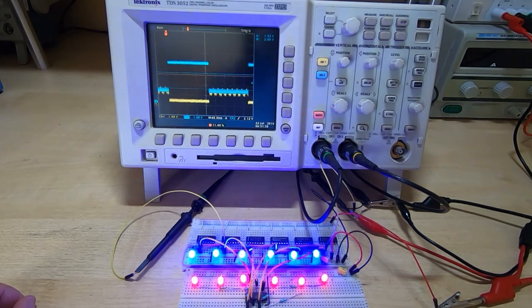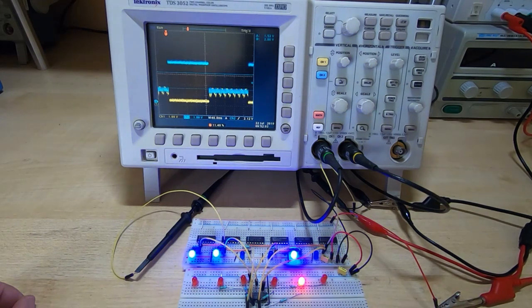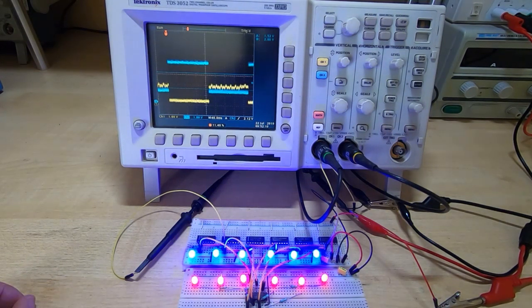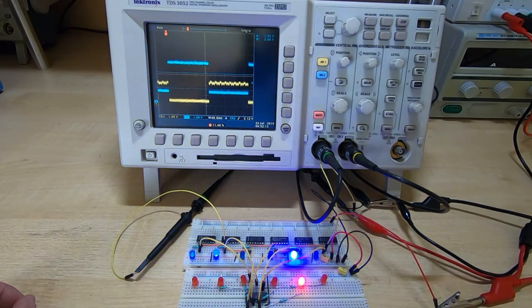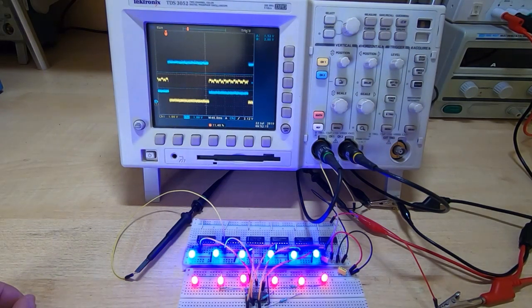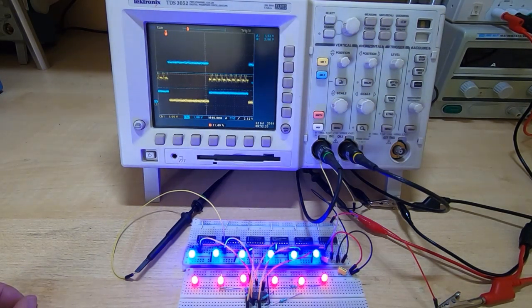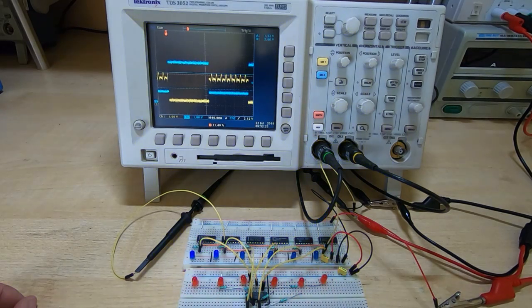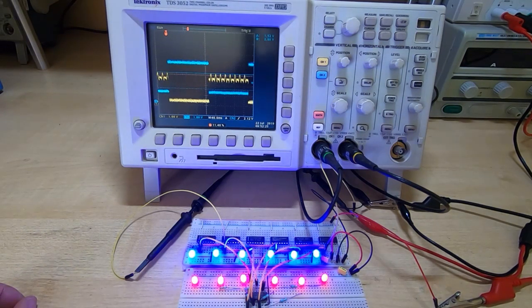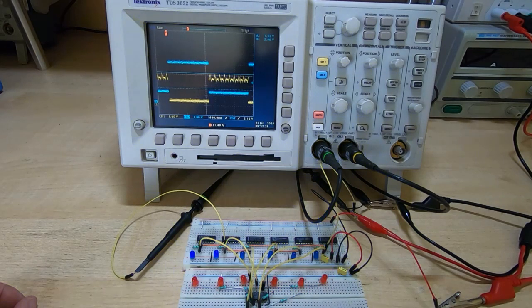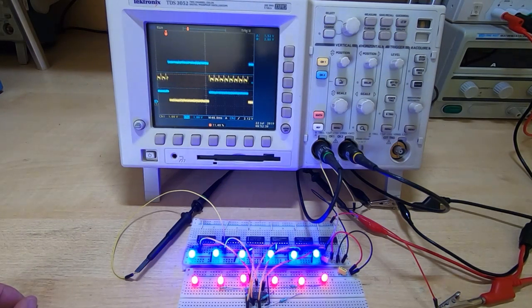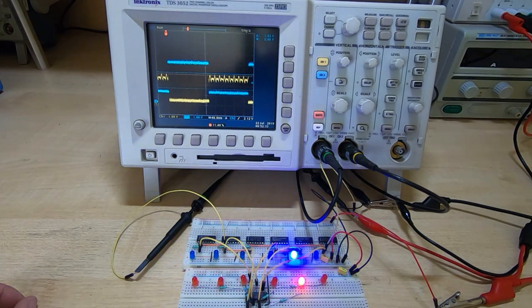If I start to lower the swing, or rather reduce the low level so it starts to come back into its normal range, I'm doing this 10 millivolts at a time, you'll see that it starts to recover bit by bit. So unlike the HCT, which is all or nothing, it's either working or it's not, you can see that as we start to go back into the normal mode of operation, the output value, because this is the output we're looking at, starts to increase incrementally.